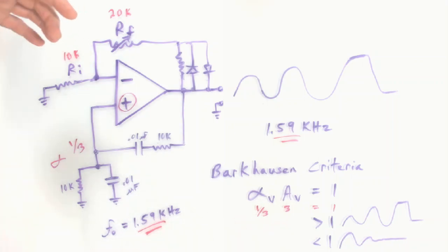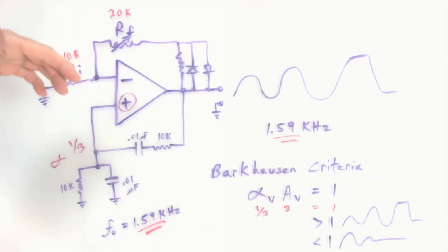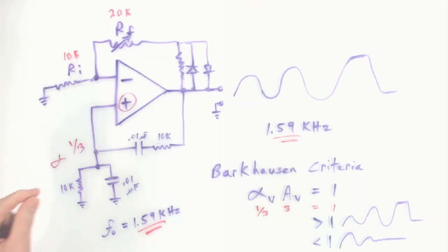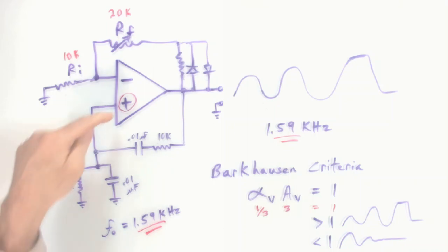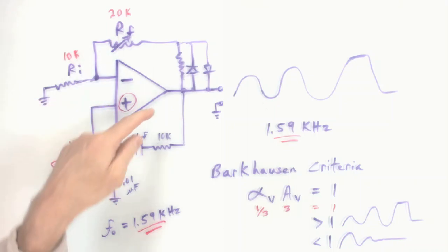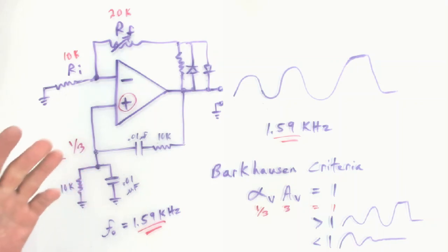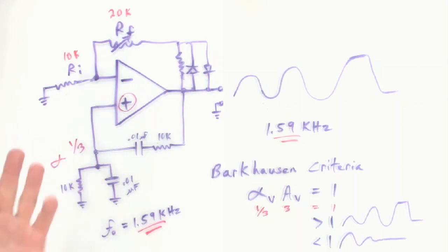But again, it's just these ingredients. You're going to review it. If you want to create a feedback oscillator, first thing you have to do is create an amplifier, and then add positive feedback to it. And the positive feedback has a couple characteristics that it must have. It needs to be in phase. That's why we're bringing it to the non-inverting input. But your network here can't have phase shift, or I should say, it should have a net phase shift of 0.